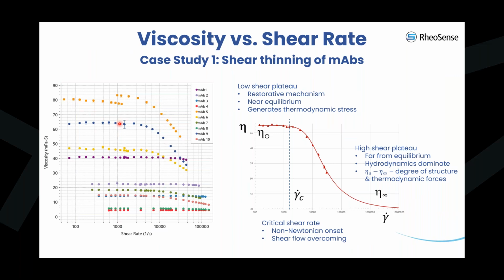And also the difference between viscometer and rheometer. Rheometers can give you more information about G prime, G double prime properties of the sample, the oscillatory properties, because in those instruments you can apply oscillatory deformation to the material.